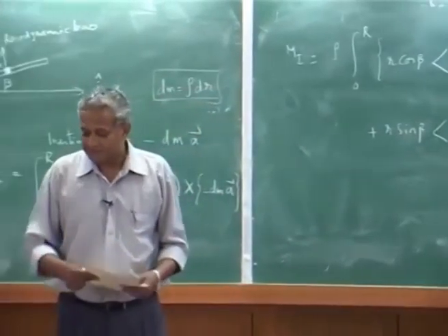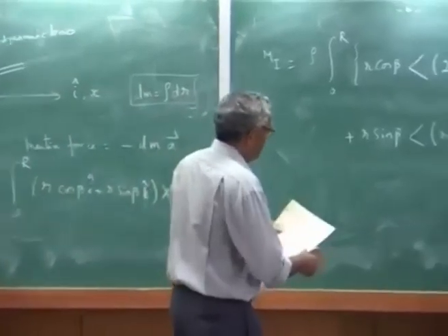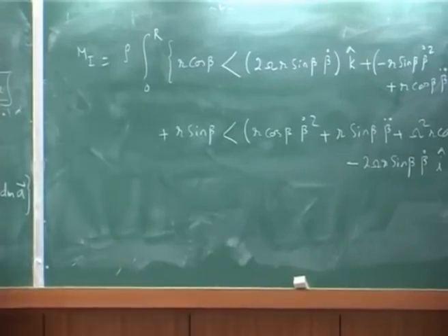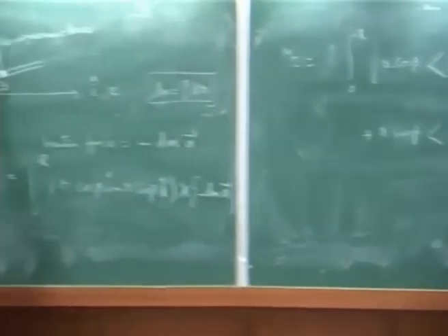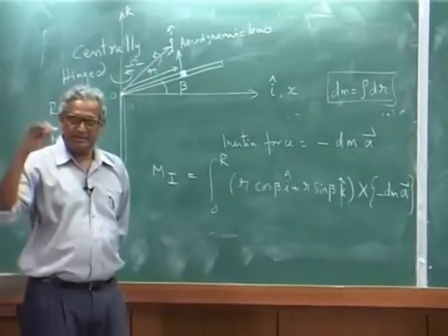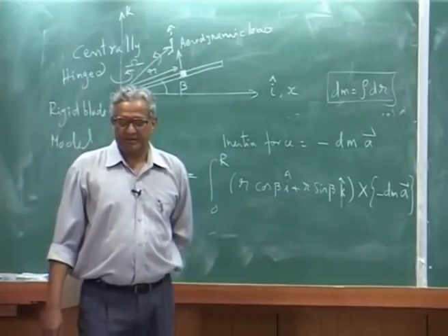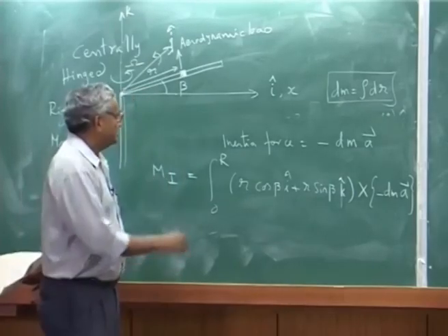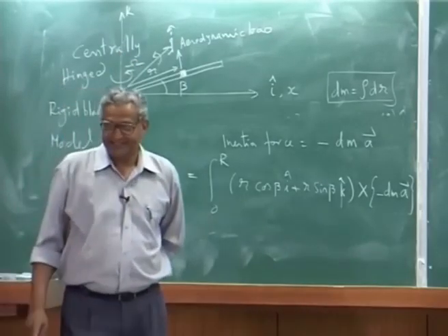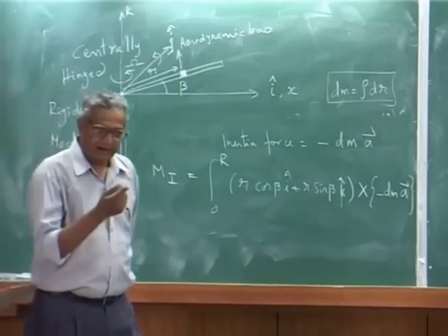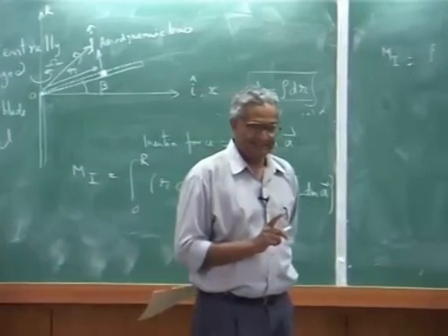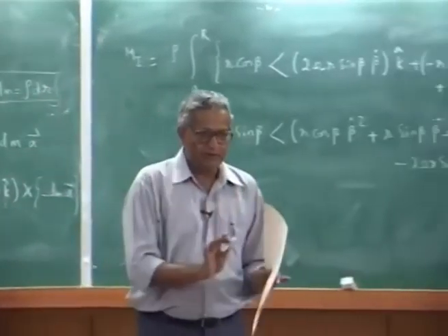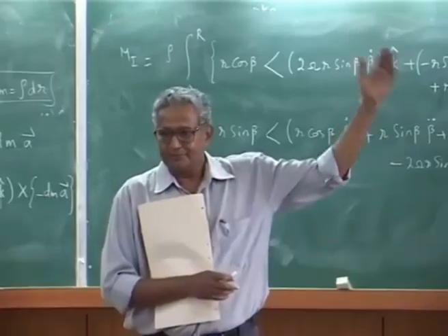If you simplify, I need the equation of motion only about the j axis, because even though I may have moment about the k axis, I don't take that into account, since I am writing the equation only for out-of-plane motion.